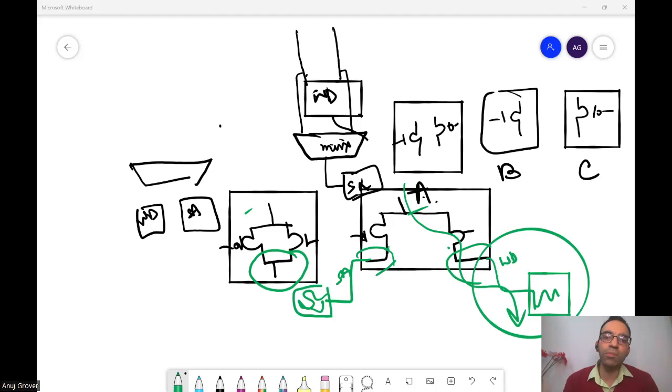Yes, the signal that is going to the PMOS will include whether it is a read cycle. If it is a read cycle, only then that will turn on, and the NMOS will turn on only when there is a write cycle. So if this particular transistor is not even on, then what happens? Then the bit line would see only this part of the capacitance.